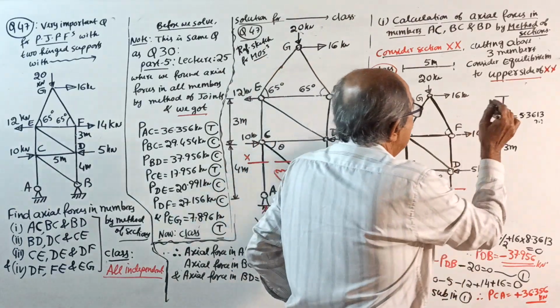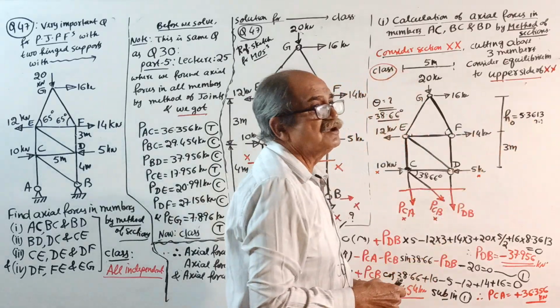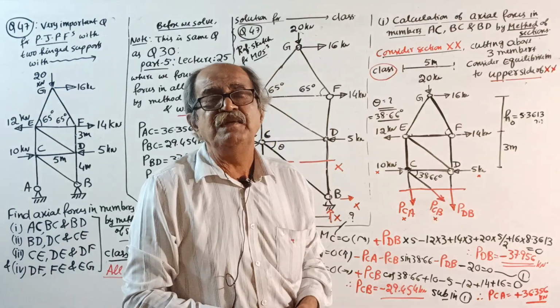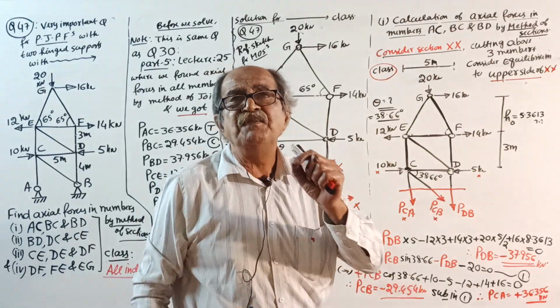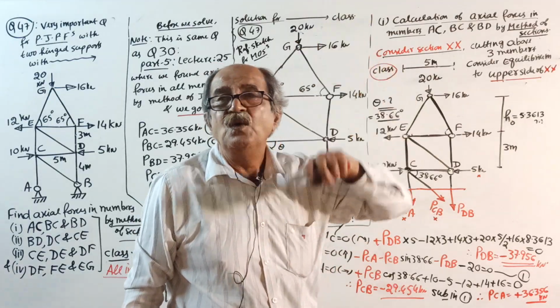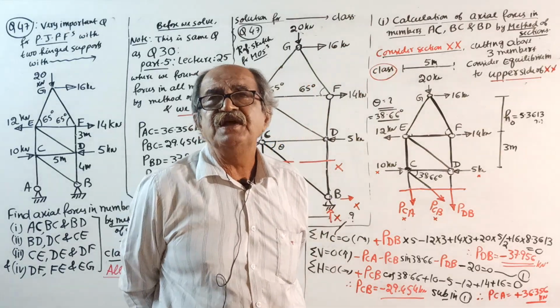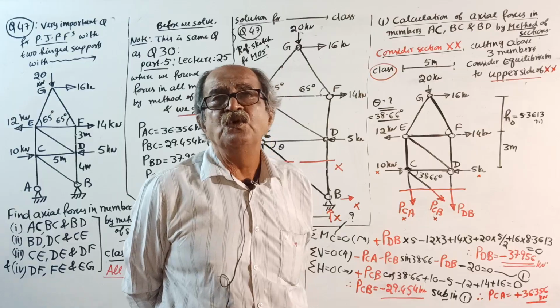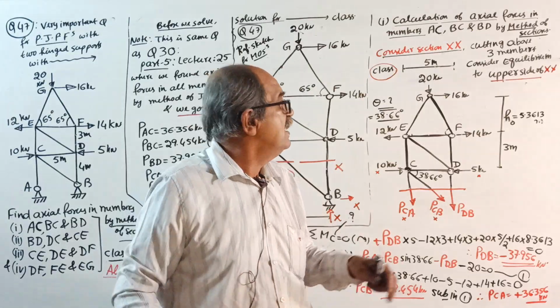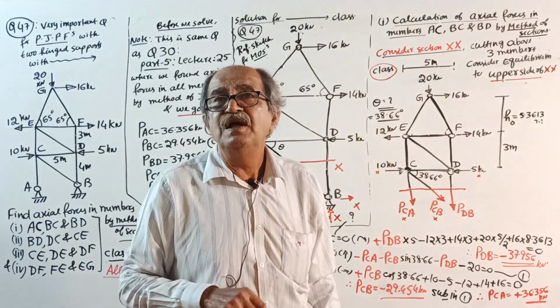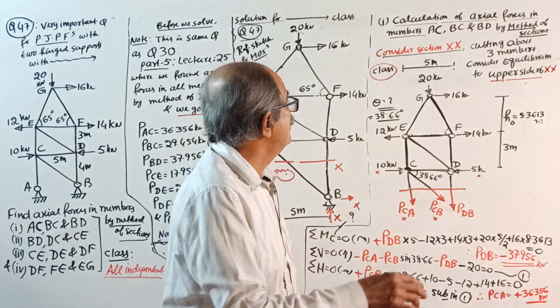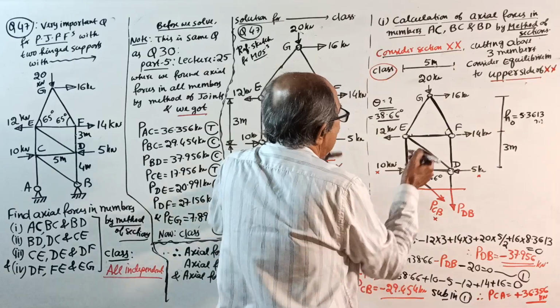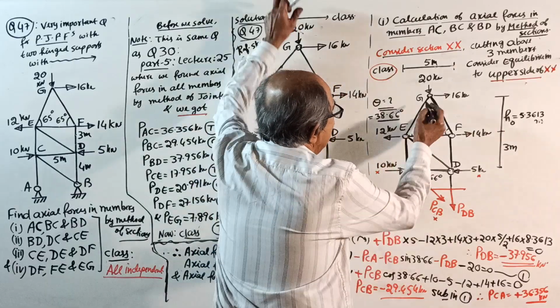Let that height equal H0. Why am I writing H0? Because I am reserving H for later. When you go for the method of section, when an unknown force's perpendicular height H is required, I am using green color at that time. I am reserving H for that one. So calculate H0; you can calculate it here only.